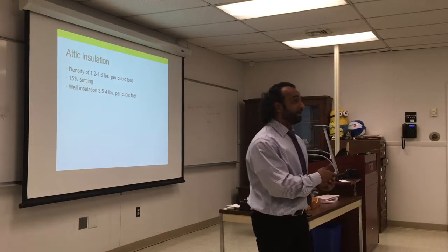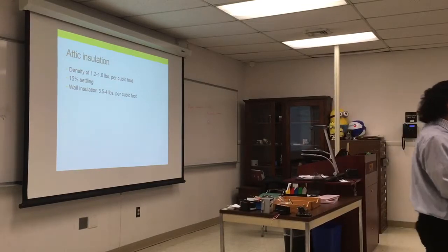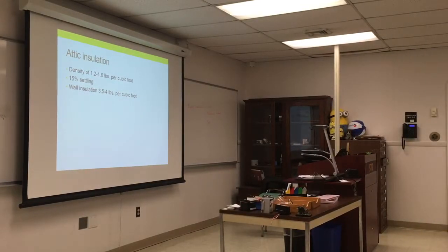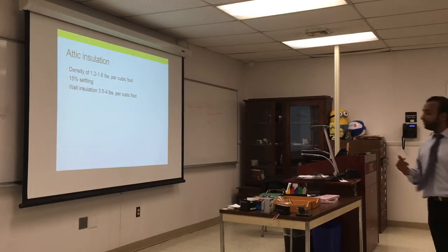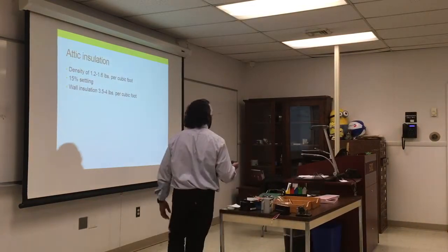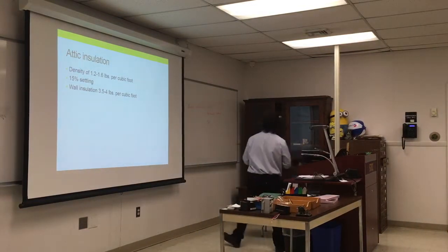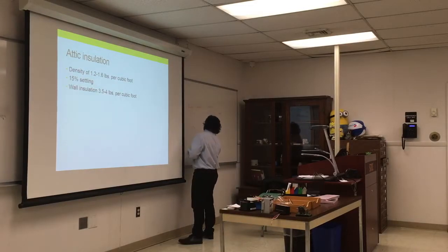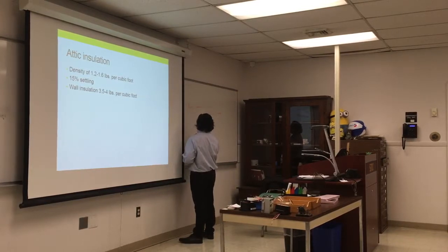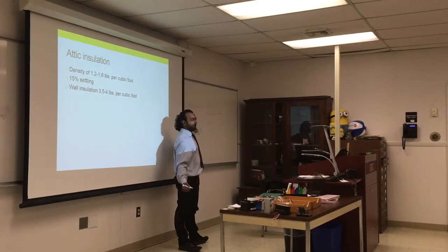So what Joe is saying is that when you want to use the chimney effect to cool the house in the summertime, you have a big vent from the attic to pull air through the house. That's used for cooling. The vent is coming from the attic outside, not into the attic, so you're not doing a push pressure. So if we have a house, you can put a vent in here, and you have vents through here, so the air will go to the outside from the attic and be pulled.